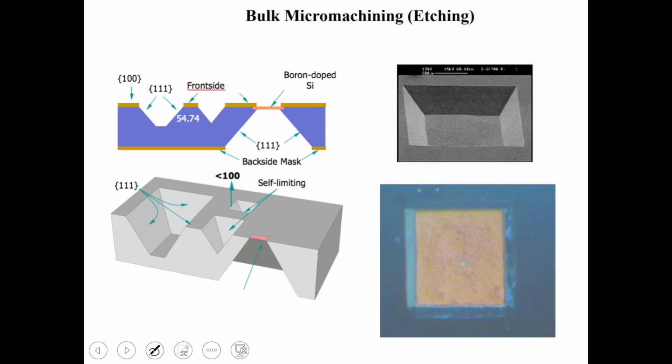So this is the fabrication part. Bulk micro machining will be used, MEMS technology. Bulk micro machining and surface micro machining are two different technologies in MEMS. They have the cut here; this is the back side mask, this is the boron dope, this is the front side, and they have the cut here. This is a P or N type cut for the P and N junction, and after that they fabricated that pressure sensor. This is the schematic and the real image of the device they fabricated.